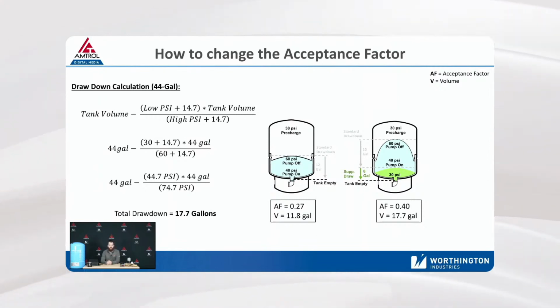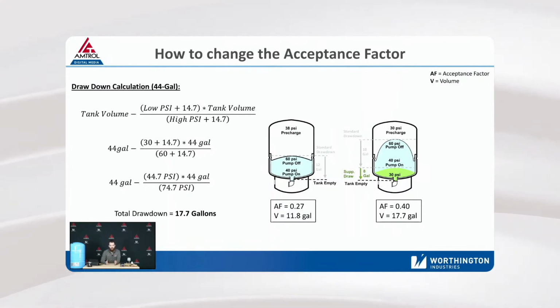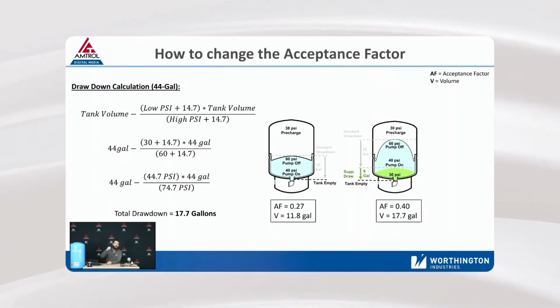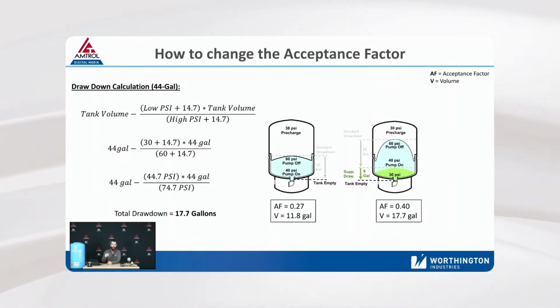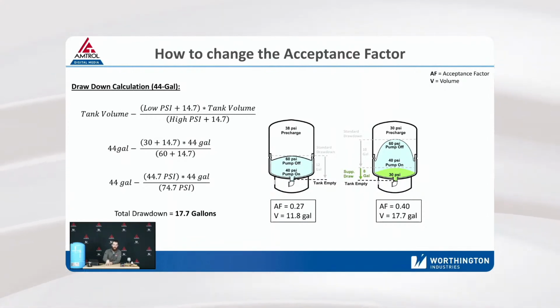So if it's a commercial system, or maybe filling a tub, I guess that would be an example, just anything where you have a high flow for an intermittent period of time. That's where supplemental drawdown is key. You're not using it every day. You don't need to always have that volume utilized. But if you're going to exceed your pump demand and you know your pressure is going to drop below, and your pump can't keep up, you can use a tank with supplemental drawdown to make up that difference. And again, we'll give examples, but that's where this is going to lead.